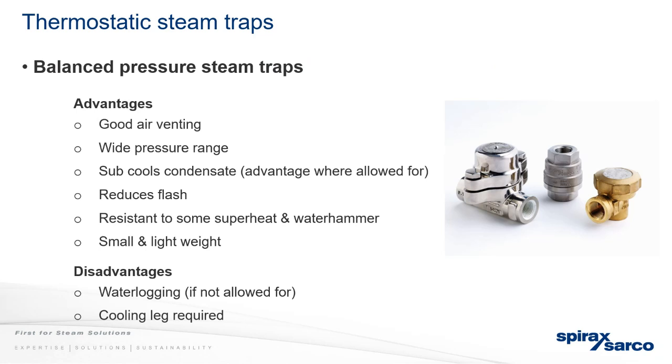So the challenge we have is a lot of steam traps tend to be quite high because our steam lines tend to be quite high. If you can extend the pipe down to the trap to bring it down to ground level or somewhere nearer, it's more of a health and safety advantage.